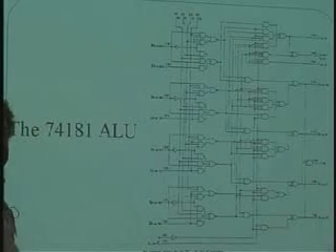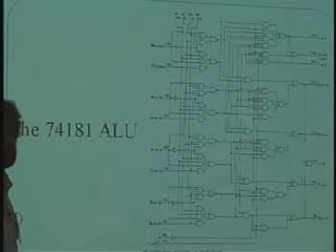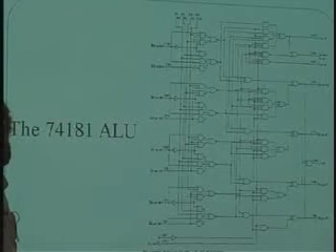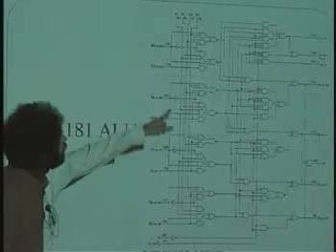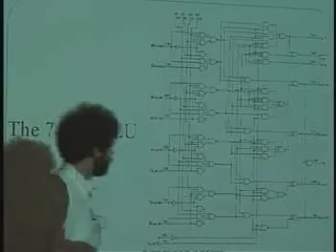And you can extend this to 32 bits without it going insane? Well, it gets really big at 32 bits. So do you know what you do? You actually build a tree of generate and propagate things. It's not quite as fast as if you kept on broadening that out more and more up to 32 bits, but it can be faster.